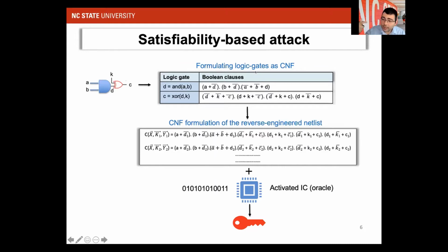And the idea is to evaluate all possible inputs and outputs formally of these two versions of the circuit, such that you can efficiently brute force the secret keys, right? So as I mentioned, the secret keys are not unique. There are groups of different keys that achieve the exact same functionality. So the idea is to efficiently group them together and to brute force these, what we call key equivalence groups,